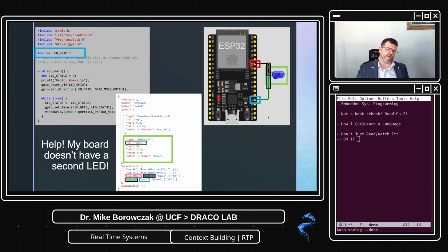All right. Well, if you thought about it for a few moments, what's missing is a resistor. One of the interesting limitations in simulators is that it's not actually simulating the physical characteristics of this LED, right? If I pump too much voltage, too much current, ultimately, into this LED, in real life, I'm going to burn out this LED. The simulator won't do that, right? So there are some limitations to simulated environments, namely that there's a chance that if I hook this circuit up in reality, it might not work. All right, so just something to consider.